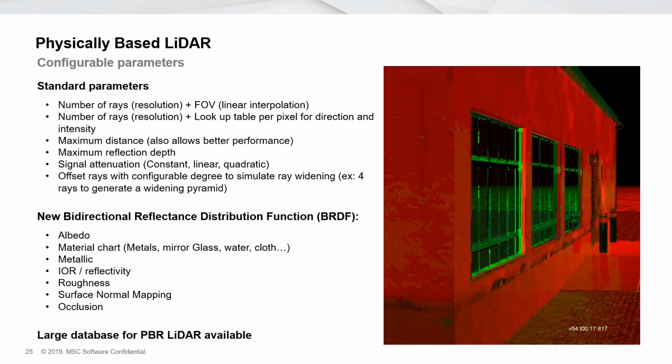So you may want to configure an offset around this ray by yourself in the simulation environment, so that when you hit an object which is far away, you will hit a cone, and the simulation environment will provide you with the information you want within this cone. It could be, for example, the highest intensity within this cone. What you would like to configure as well for the LiDAR is probably the number of hits that you want to take into account.